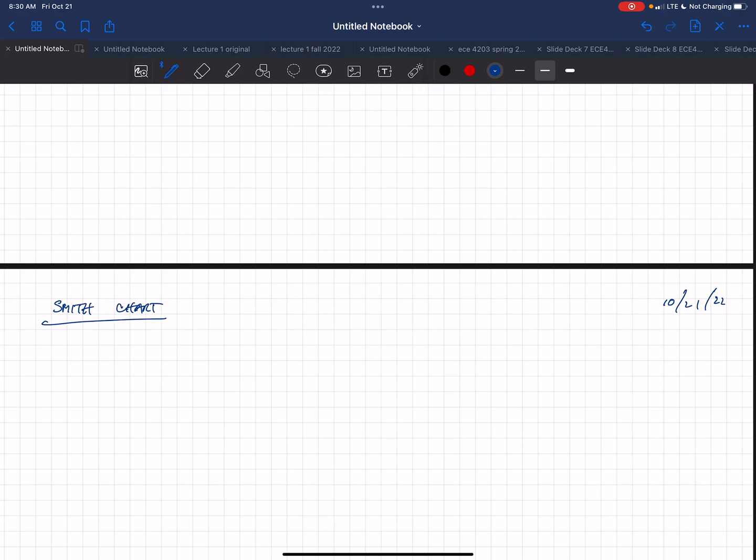But if we put in another transmission line, we get a different reflection coefficient. There are these relations, so you have those two factors: impedances and reflection coefficients. The Smith chart is a way of relating those two in a graphical way rather than doing the equation. It's not doing anything additional compared to the equations we've been looking at, but it's a way of graphically representing those.